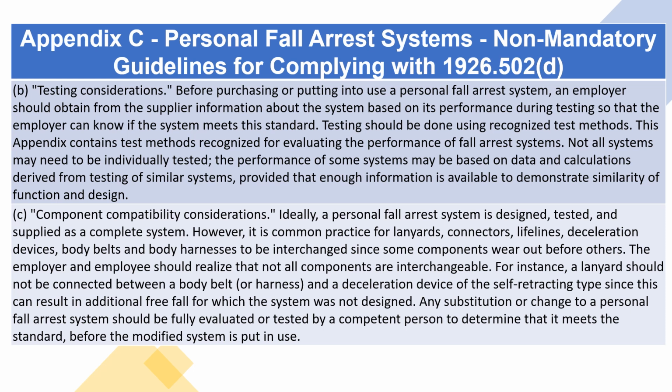C. Component compatibility considerations. Ideally, a personal fall arrest system is designed, tested, and supplied as a complete system. However, it is common practice for lanyards, connectors, lifelines, deceleration devices, body belts, and body harnesses to be interchanged since some components wear out before others.